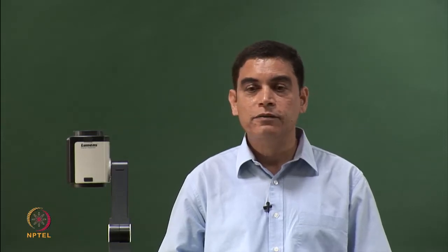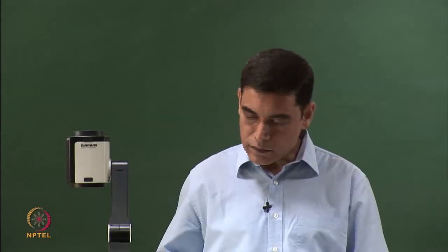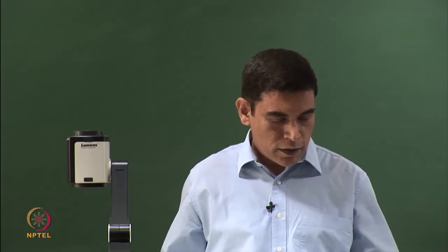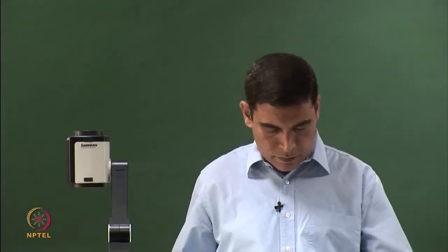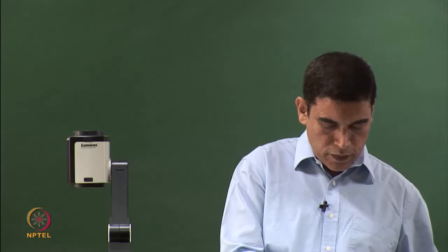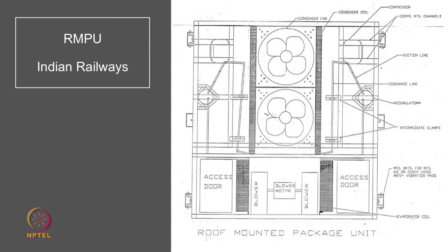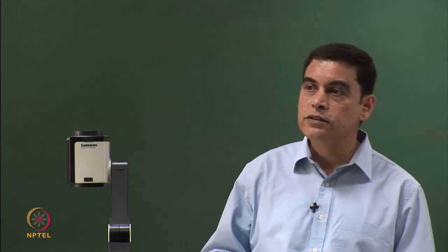So we did an experiment where we made a sub-assembly, and the sub-assembly was one part of the AC unit. So if you see the compressor here, it is connected and there was a failure happening at this place. So we just made a sub-assembly of this portion. We connected the same braided connector to the compressor, and we subjected it to repetitive shock. So there was a defense equipment which was used for validating defense units for air conditioning.